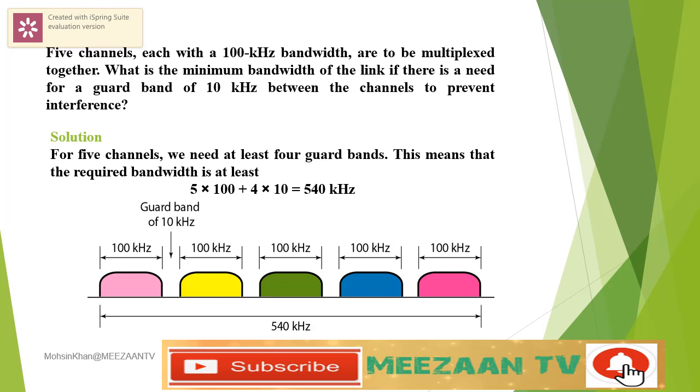Here in this example there are 5 channels, each with 100 kHz bandwidth. Since the total bandwidth of the channels is 500 kHz, the guard band is 10 kHz. Since there will be 4 guard bands between 5 channels, the bandwidth required for guard bands is 40 kHz. The total bandwidth of the multiplex link will be 500 plus 40 equals 540 kHz.